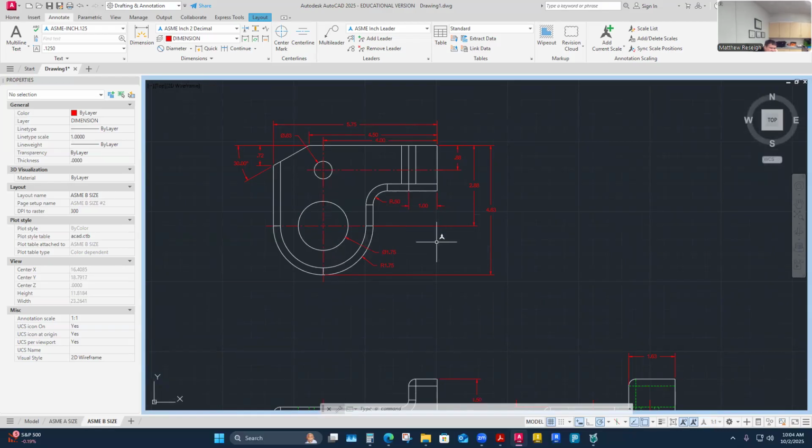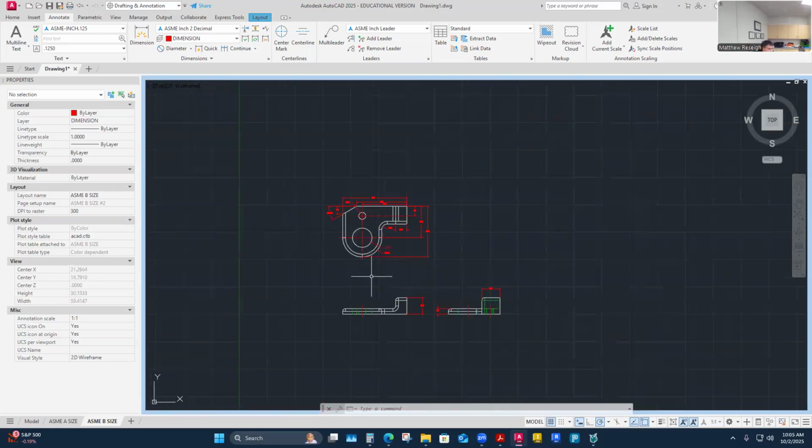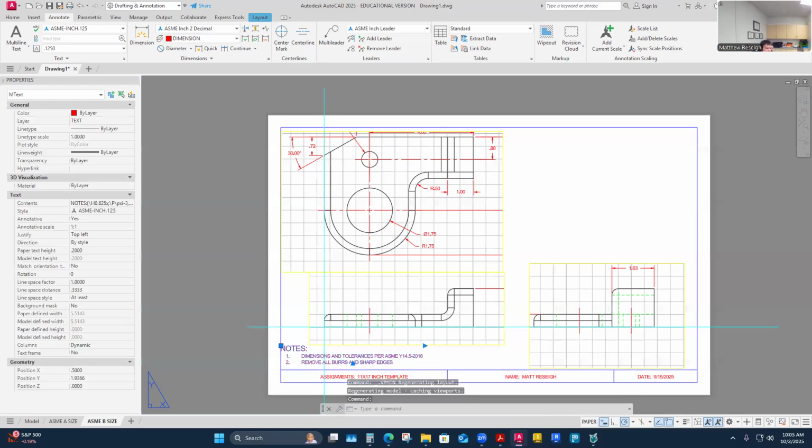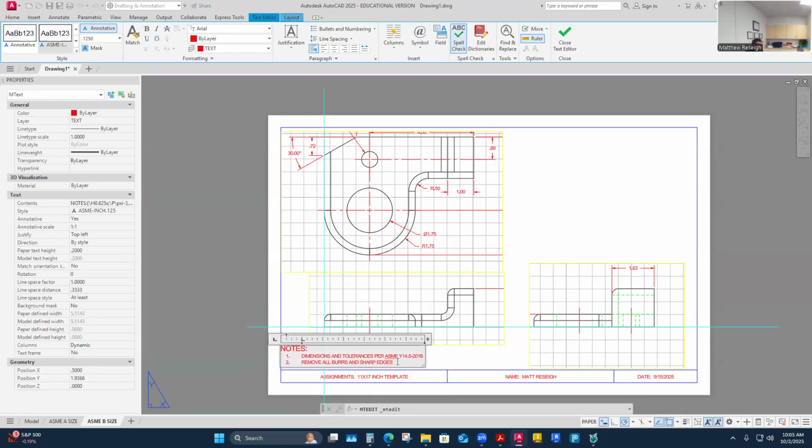And then I think about any other features that I have. Well, I have all the radiuses, but I think I'm going to carry those in my title block in my notes. While I'm thinking about them, these features of this part are the radiuses that I've had difficulty drawing and have probably led you down difficult roads as well. I'm going to carry that, but while I'm thinking about it, I'm just going to jump out and make that note adjustment so that I don't forget later, because I'm thinking I need to have those located or I need to have their sizes called out. So while I'm thinking about it, I'll come down here and say rounds and fillets, radius 0.25.